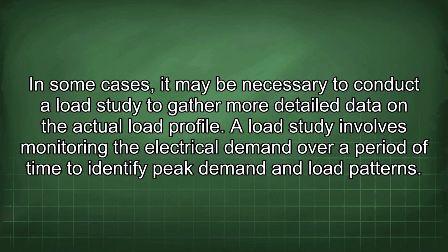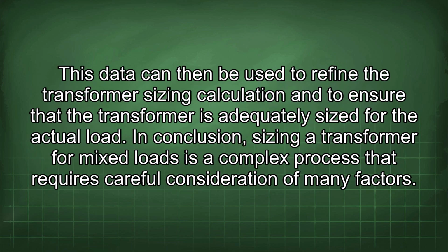A load study involves monitoring the electrical demand over a period of time to identify peak demand and load patterns. This data can then be used to refine the transformer sizing calculation and to ensure that the transformer is adequately sized for the actual load.